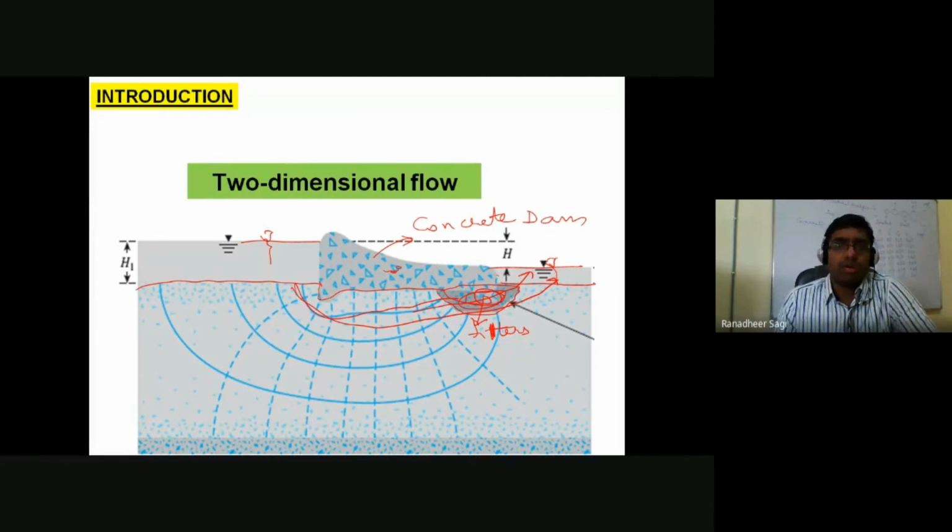So what is going to happen here is, as I have earlier discussed also, along with your water particle which is trying to get dissipated out of the soil sample when it is moving from upstream to downstream, because of the movement of your water particle as the seepage is happening through the interconnected void path, along that water particle movement, if there are some fine grained particles which come into the flow region, those fine grained particles also sometimes get carried away along with your water particle.